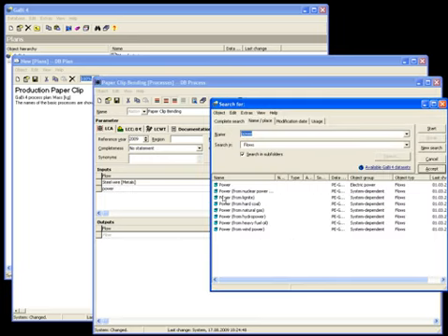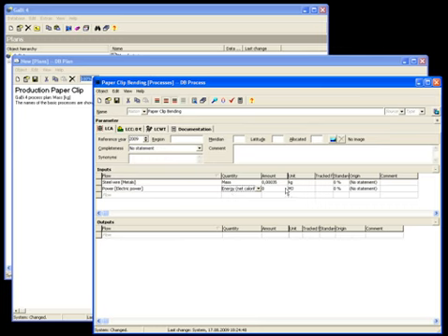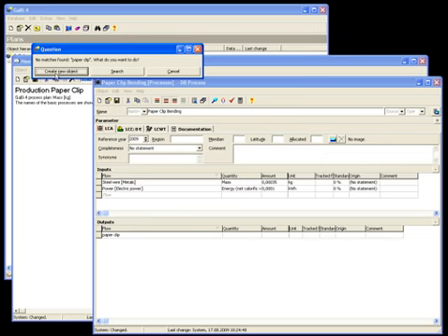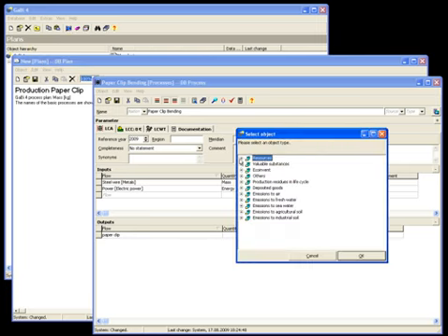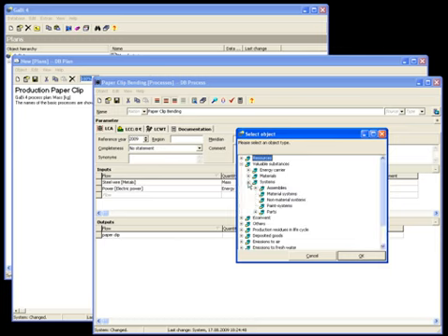The best match can be selected and entered in the process by double-clicking. The appropriate unit can be selected, and the quantity entered. If no match for the entered flow name is found, a window appears asking if this new flow should be added to the database. Since there is no paperclip flow available in the GaBi database, it can simply be created from within the process where it is required. Of course, a new flow can be created at any other time too.